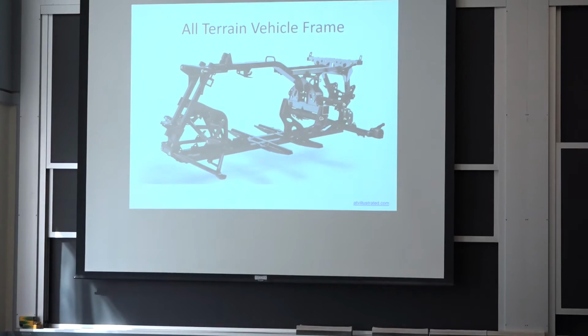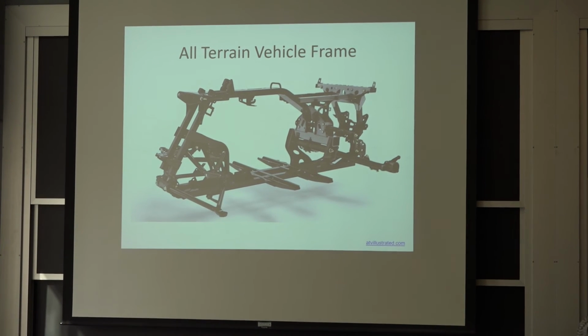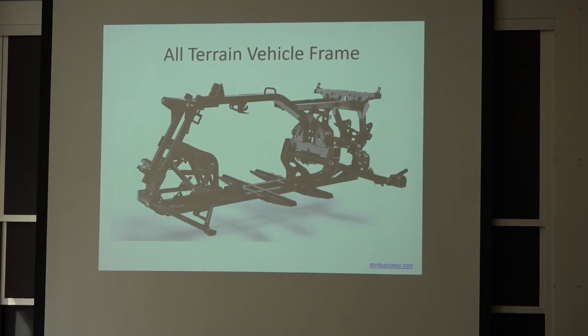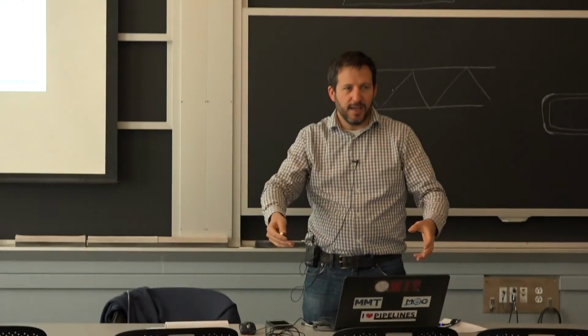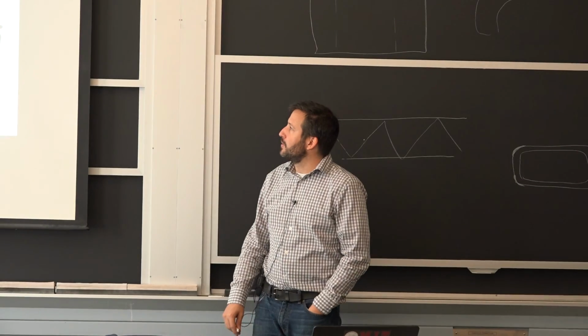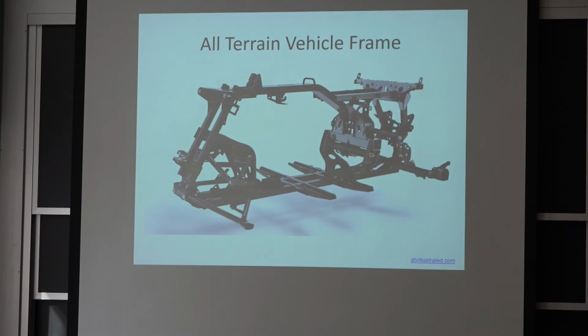And let's go back to why we do it. So this is essentially monolithic, and you have it for motorcycles, for all-terrain vehicles, cars a little bit the same. If you take all the side panels, the side body off, you have a frame that has a lot of parts that are welded together using these templates or clamping that allows you to consistently get the same shape over and over again, and you can make big production. So this specific type of body, I've seen it done, and they will do, let's say this could be done in 5 sub-assemblies.